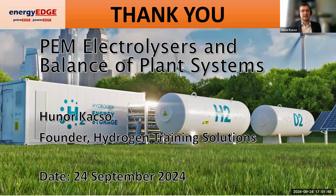The trouble is, the higher you go, the more risk of membrane degradation on the stack. The higher the temperature, the more risk of hotspots on the stack, which is one of the main degradation mechanisms of PEM stacks.